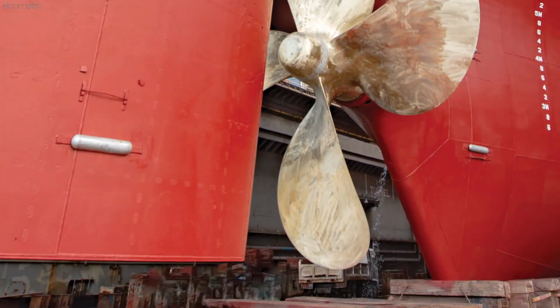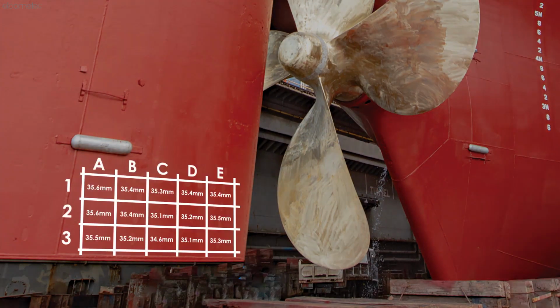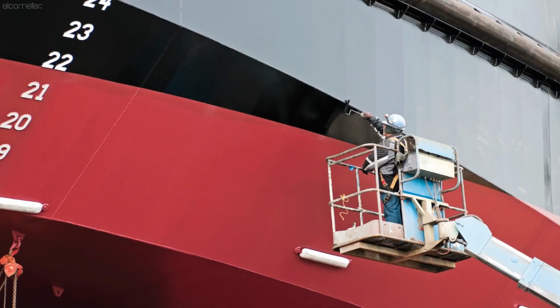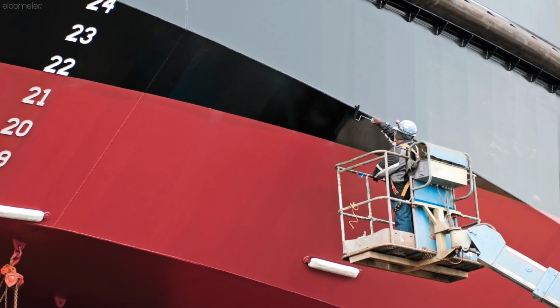Using a grid allows you to inspect large areas in an organised way, clearly mark and identify areas of concern, and helps you to easily report to the asset manager exactly where corrosion is occurring. Also, by repeating grid-based inspections in the same location over time, this allows you to predict corrosion rates and perform preventative maintenance to avoid a breakdown.